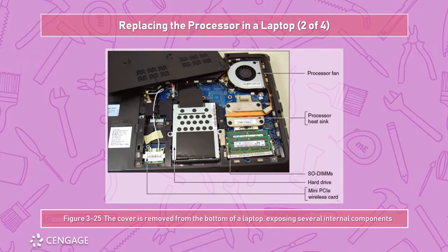That is going to contain a very volatile liquid that very quickly turns from liquid to gas when exposed to heat. That means that the pressure will increase. It'll move towards an area of lower pressure, which is usually going to be where the fan is. It'll cool the metal, and then it'll condense and flow back. So you set up a convection current in order to enhance the cooling.